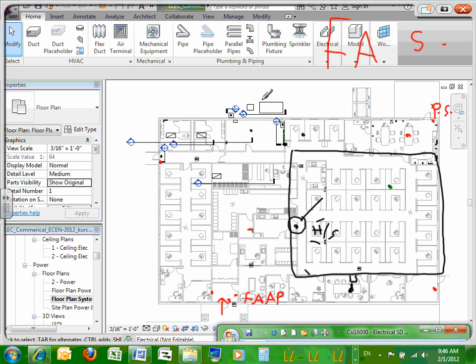So these other Simplex ones here for smoke detectors, I think what we said, there's 30 by 30 if it's a rectangle or a square, or a radius of a circle of 21 feet. And 21 feet takes into account different ceiling heights, so it's almost got a little bit of a fudge factor in there. But what I do when I lay out smoke detectors, there's our coverage, and that is 21 feet, the radius.